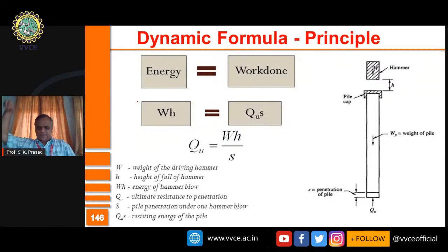On the other hand, if the driver can penetrate very quickly, it indicates that the soil is softer. Therefore, we may be in a position to use the driving energy to determine the capacity of the soil, and this is called dynamic formula. So whatever energy is required, it is the work done basically. Work done is WH, and to that work, the pile will experience some settlement.